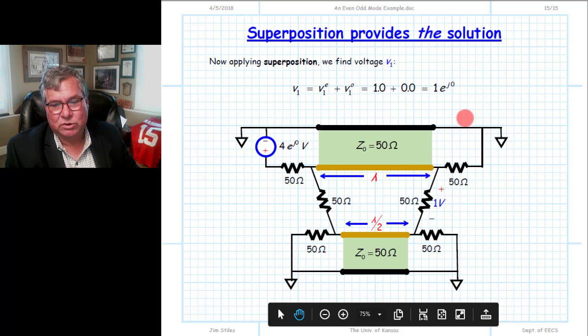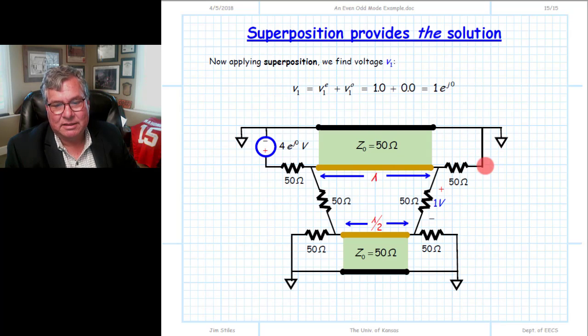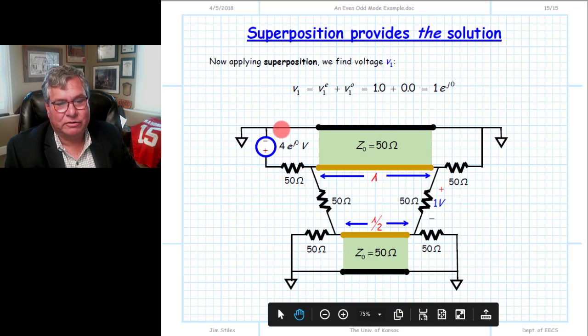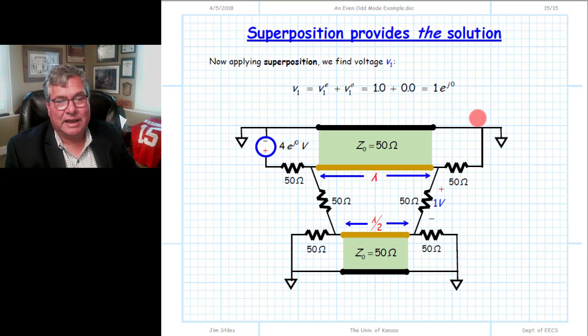It's this voltage source reflected across over here. This is where we need to do our odd-even mode source magic in order to apply our superposition. And that's the real trick of these problems, finding the boundary condition and figuring out where to add in the odd and even mode voltage sources. Usually after that, the circuit will simplify very quickly and very easily.